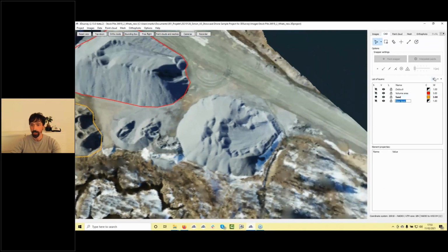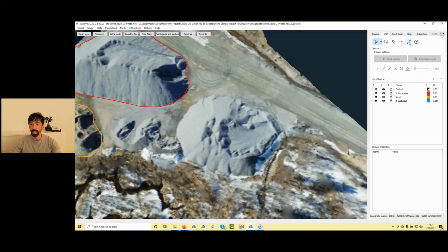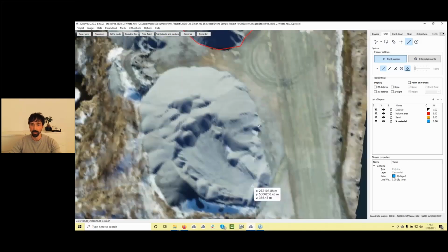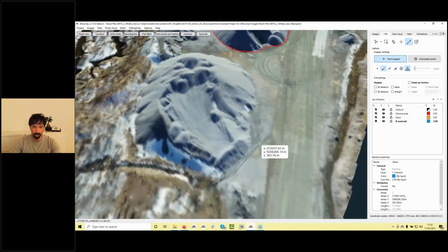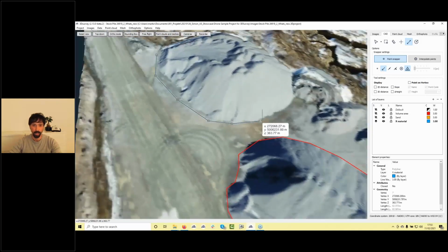And here create a new layer, X material, I don't know what this is. Let's make the layer active, set the width of the line to 3, and I will use, let's say, blue color. Then I will select my draw line tool and I will snap on triangles and endpoint. I don't need to display distances. So what I'm going to do now, I'm just going to draw the CAD lines.